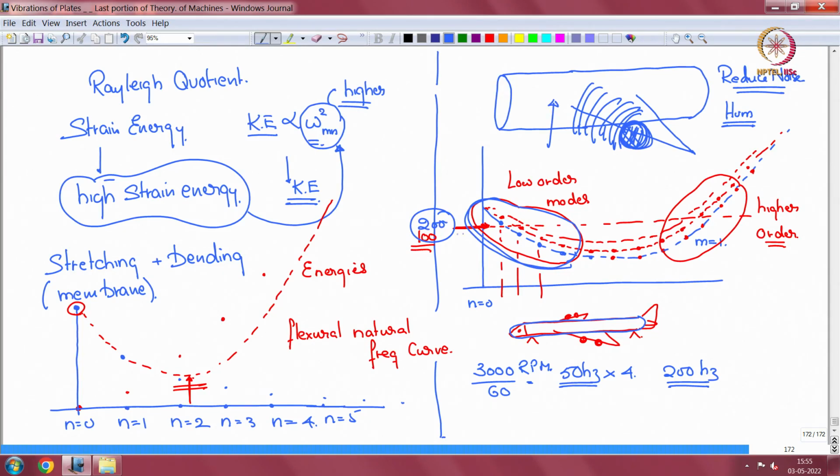Okay. So now around 200 hertz there are that many modes. You could have 100 modes. So that many modes are now responsible for transmitting, that means the shell vibrates. This is shell vibrations, and the vibrations in turn send sound inside the cabin. But suppose now you have some strategy of reducing these modes, by some active means, by putting shakers or acoustic speakers inside the cabin, to try to reduce it.